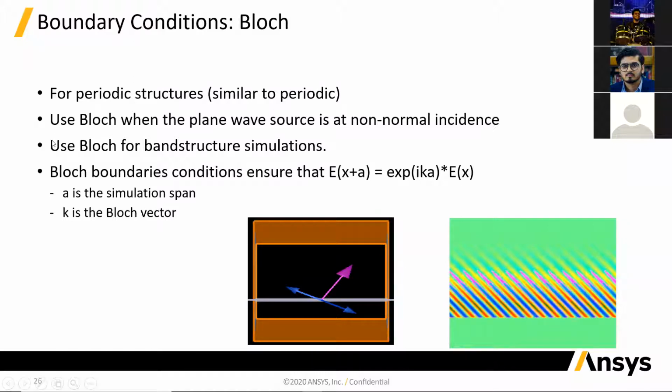So block boundary conditions can make your simulation run slower. In a lot of cases, if you're running periodic boundary conditions with single frequency sources, a periodic boundary condition is enough. However, if you have a broadband simulation where light is getting injected at an angle and the phase is critical, then you often have to use block boundary conditions.